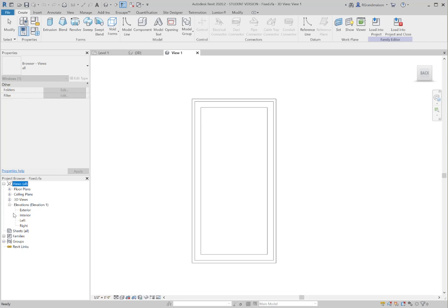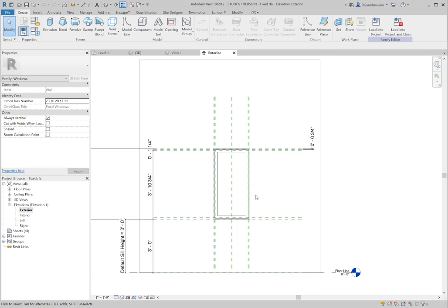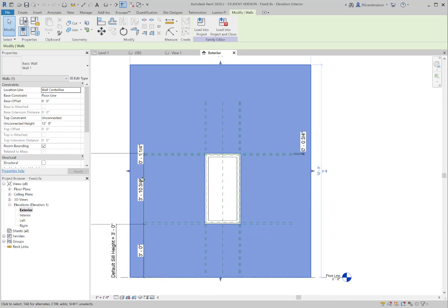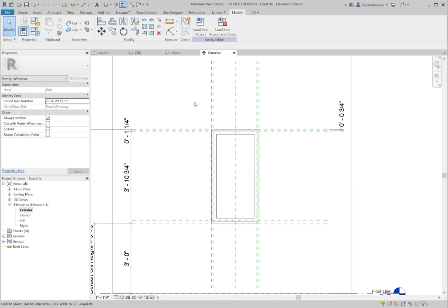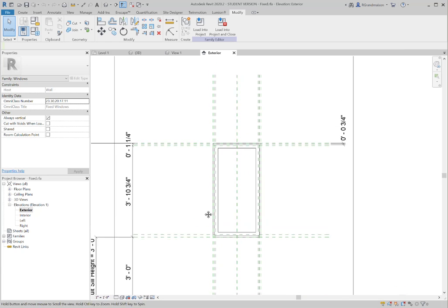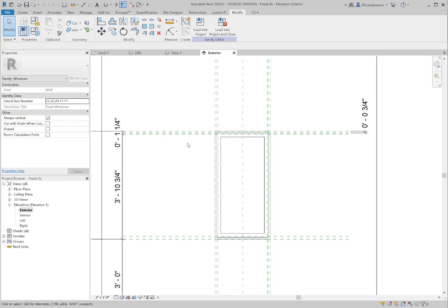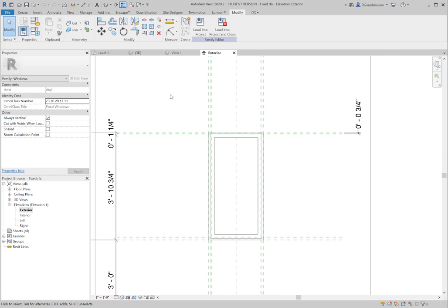Right now I'm in the 3D view, so as soon as I switch to a true orthogonal exterior view, you'll see a lot more information here, including the temporary wall that the window cuts the opening for, and all of the reference planes that were created to define the components and align and lock the geometry of this window frame and sash. And the glass as well, probably. So I'm going to go ahead and build some new reference planes in here to start working on this process.